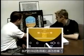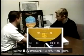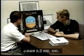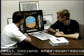What about our magenta sword or dagger here? That's the ILS course selection, and this is on scale, this is off scale. Again, how would you get this display? The ILS push button has to be selected on. Good. In which case, as you said before, we get our raw data glide slope and localizer.